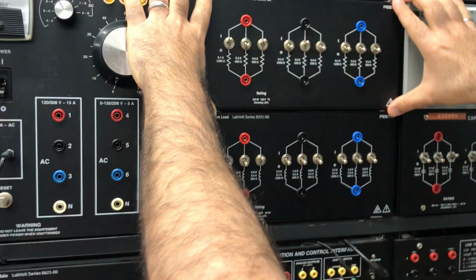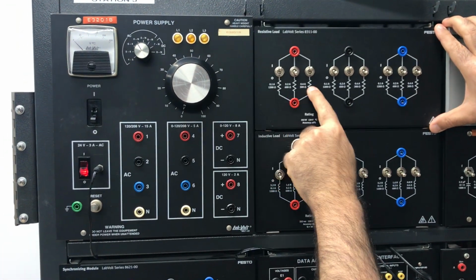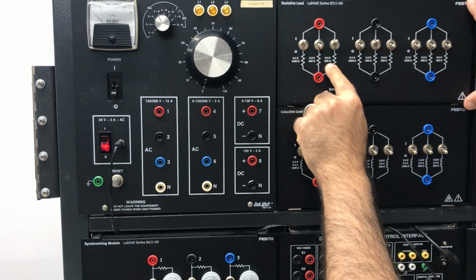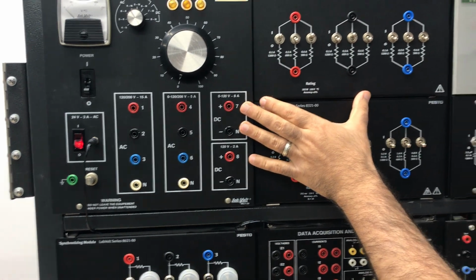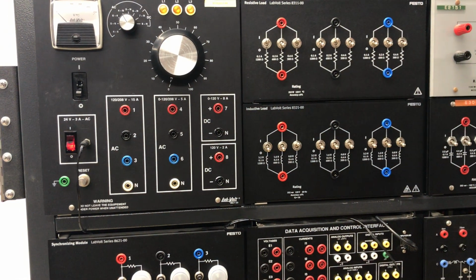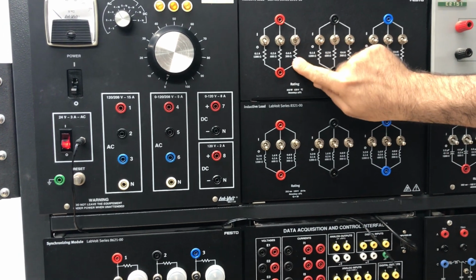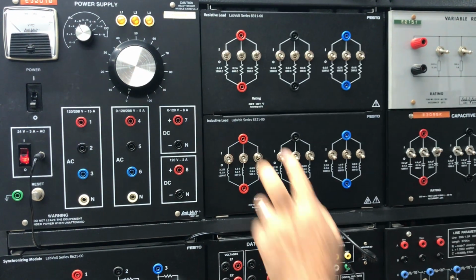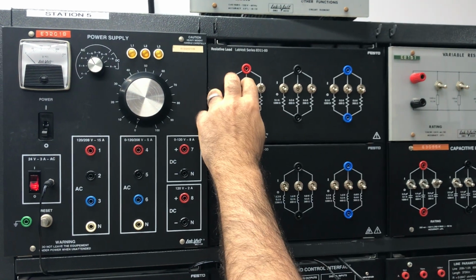Let us talk about this resistive load. Because this is educational, we connected three different resistors: 1,200, 600, and 300 ohms, and those are repeated because we are going to use them in a three-phase. But we are going to use this set for different values of resistance. If this one is on, it means I have only 300. If this one is on, I have those connected in parallel. If this one is on, I'm connecting all of those in parallel, and I'm taking the total resistance between these 2 points.